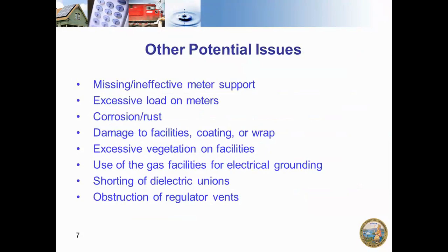If you do any more than that, you're often overloading your cathodic protection system, and it will bring down your reads. Just a couple shorts can bring you out of compliance across your entire park. So it's definitely something you want to keep your eye out for.